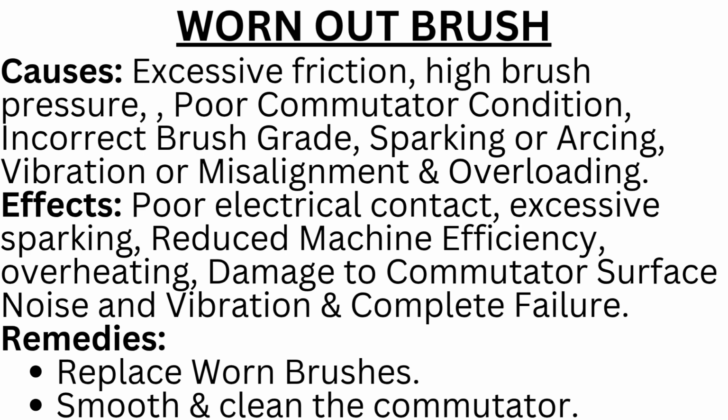Causes. Excessive friction, high brush pressure, poor commutator condition, incorrect brush grade, sparking or arcing, vibration or misalignment and overloading. Effects. Poor electrical contact, excessive sparking, reduced machine efficiency, overheating, damage to commutator surface, noise and vibration and complete failure.